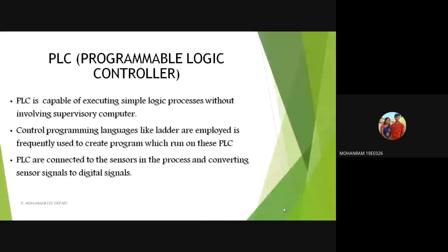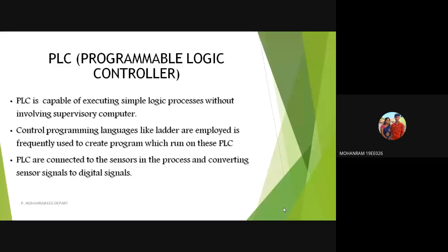The programs in the PLC can be modified online without stopping the PLC. The working of the PLC need not be stopped for programming it. It can run on the side, and it can be recoded or reprogrammed online. The programming language mostly used is ladder. Ladder is majorly used because it is an easy language for users to code, and the language resembles the structure of a ladder, with two vertical rails and a series of horizontal rungs between them.